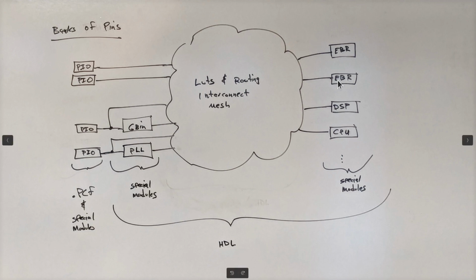So, big picture. We're going to focus on writing code that sits inside this cloud. And I would love to start here. I would love to focus on that and get into it, right? The problem with that is that you can't really do anything with an FPGA unless you're connecting up I/O pins, because any circuit that has no inputs and no outputs doesn't do anything. It's not fun. In fact, the compiler will figure out that it has no inputs and outputs if you create such a thing, and it will optimize that all the way down to not doing anything because it has no purpose. It doesn't take a lot of optimization to do that, but that is what will happen.